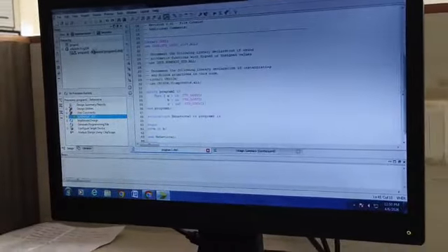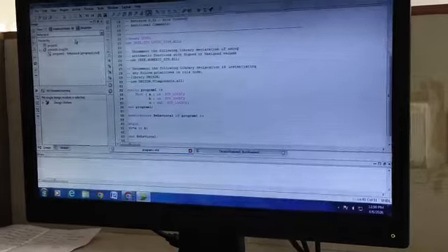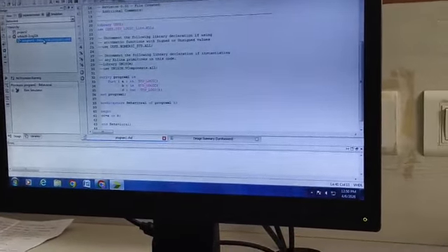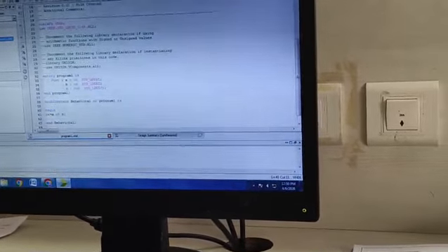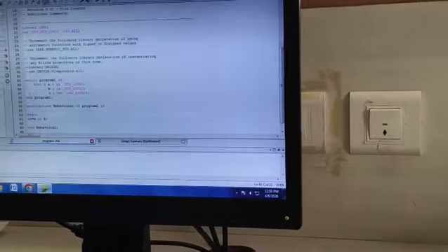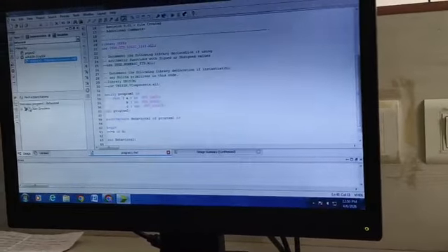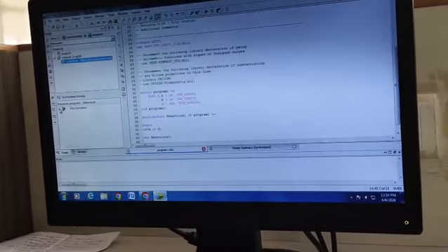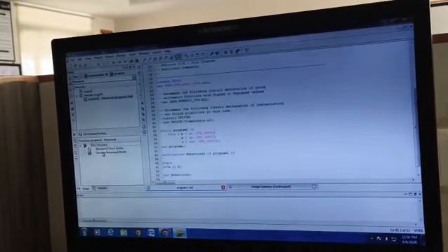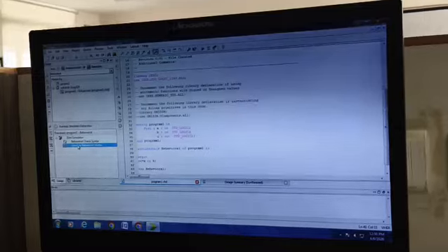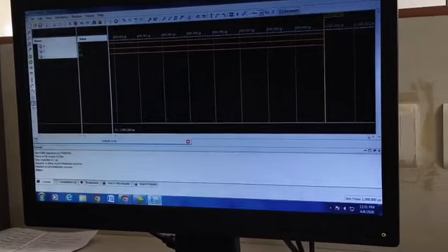After synthesizing, we go to simulation. Click Simulation and select the program, behavior 1. Now this program is selected and ready for simulation. Expand the ISim simulator window, and double click Simulate Behavioral Model. The graph window will open.